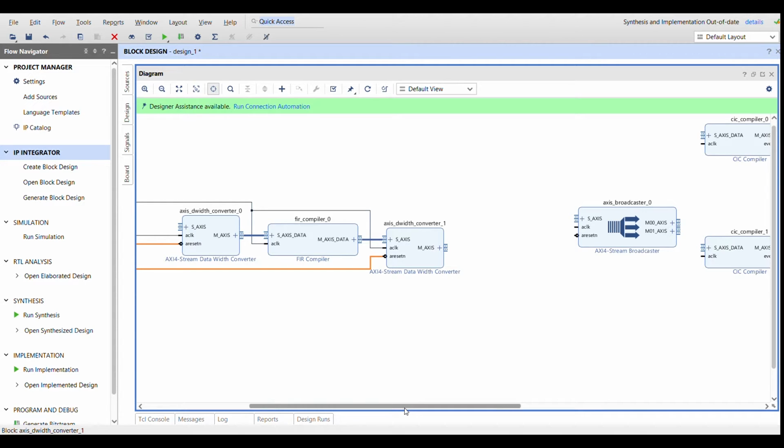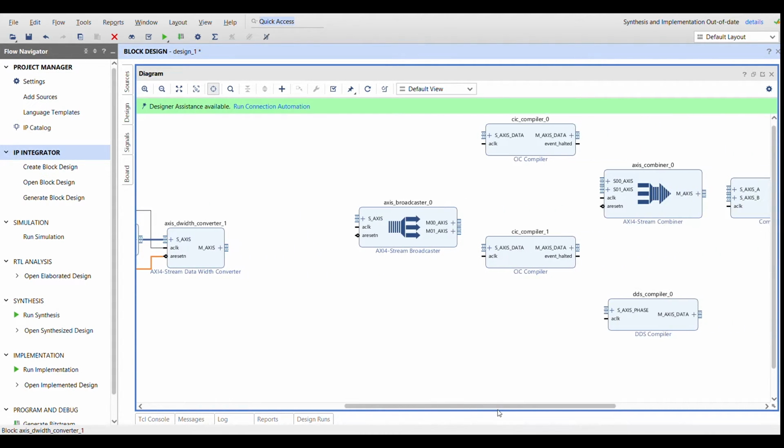The next stage is we're going to go to the CIC filters that will convert the data to the final 122.88 MHz sample rate that we need for modulating the local oscillator DDS. There's 2 scalar filters, one for in-phase samples, one for quadrature samples.